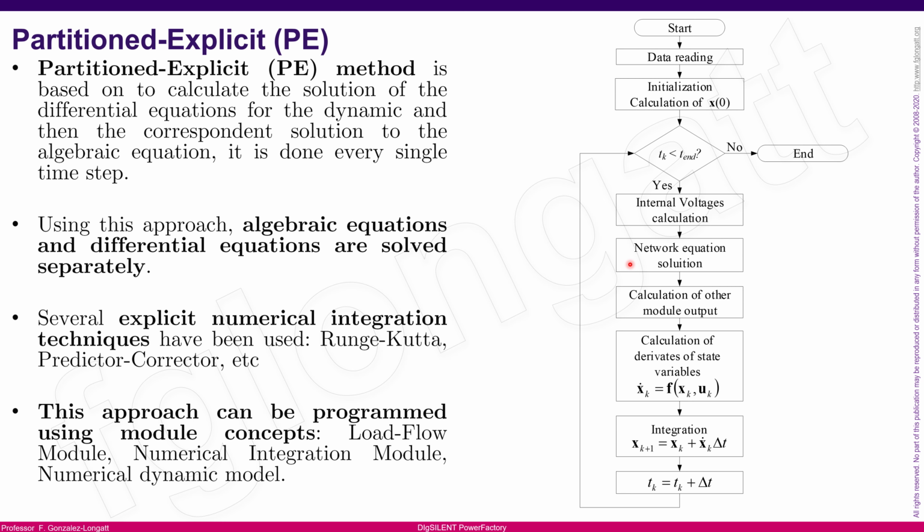In general terms, what we are doing for the network, for the algebraic equation, is using numerical methods like Newton-Raphson or something like that, okay? Here we have the flow chart, and the flow chart typically shows the process that we use to solve the differential algebraic equation model using the partition explicit, okay?